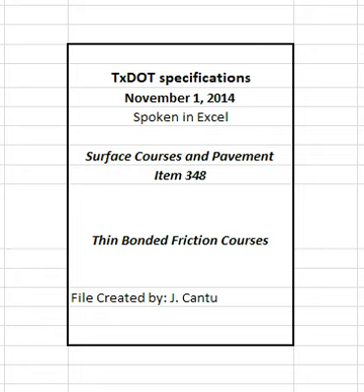However, a failing spot check will require confirmation with the stockpile gradation determined by the engineer. 2.1.1.2 Micro-Deval abrasion. The engineer will perform a minimum of 1 Micro-Deval abrasion test in accordance with Tex-461-A for each coarse aggregate source used in the mixture design that has a rated source soundness magnesium, RSSM, loss value greater than 15 as listed in the BRSQC.